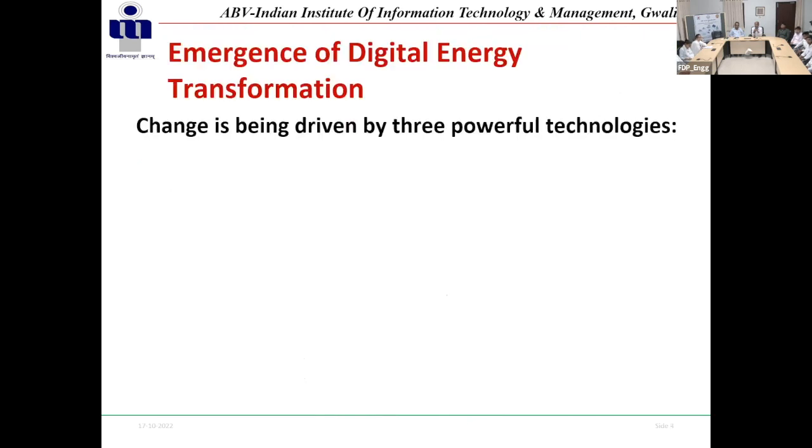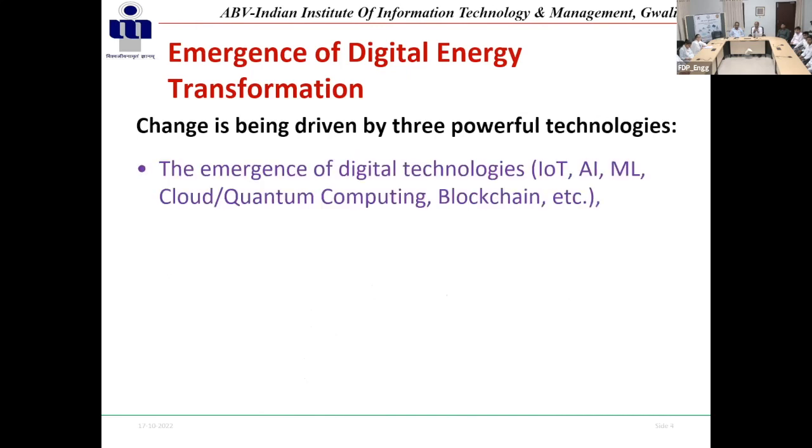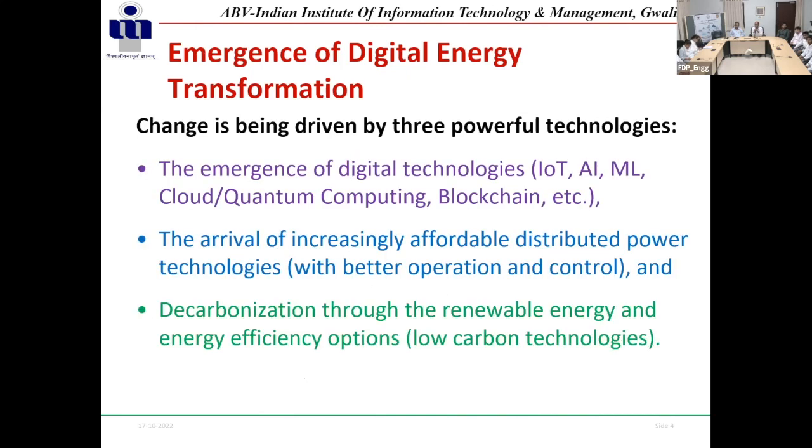Another change happening along with the renewable side is technological change. Normally we say the digital energy transformation. No doubt we require energy in a perfectly sinusoidal way, because earlier it was generated as a sinusoid. Due to power electronics, now it is not sinusoidal. Just measure anywhere near your computer center or anywhere on the campus, and you will never find a sinusoid. It is distorted because more and more DC components are being put into the system, because we are not using very high quality converters. We are using very small, even poor quality chargers, and they are deteriorating.